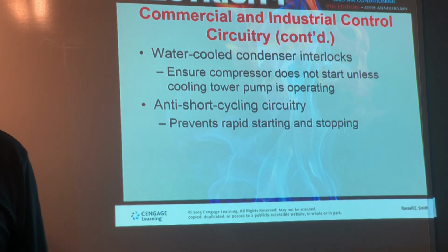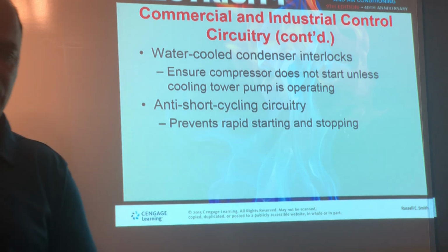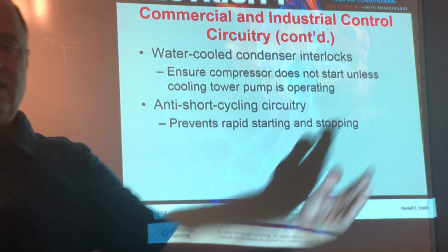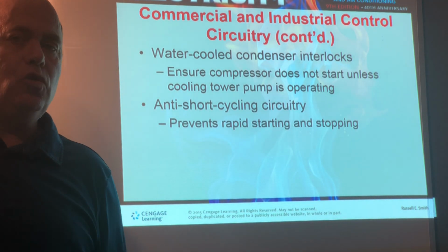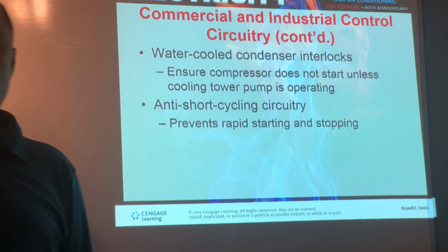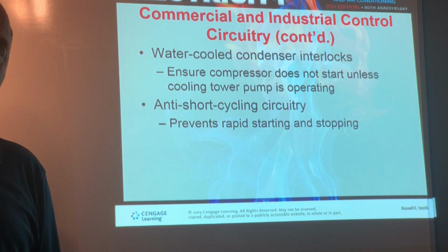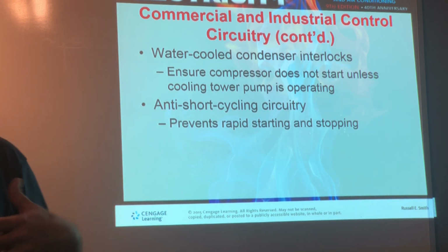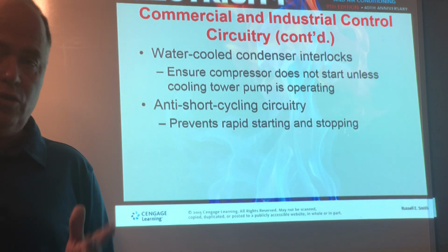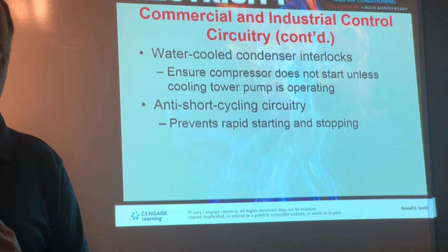There are certain high-rise buildings, luxury condominium buildings, where each tenant maybe pays for their own electricity and has a unit in the attic, and there's a little water-cooled condenser there with it, and then they pump the water that has picked up the heat to the cooling tower, and it trickles down, evaporates, gets cooled off, and gets pumped back down. So you might have 300 or 400 of these little packaged air conditioning systems with a water-cooled condenser, all being served by one giant cooling tower.